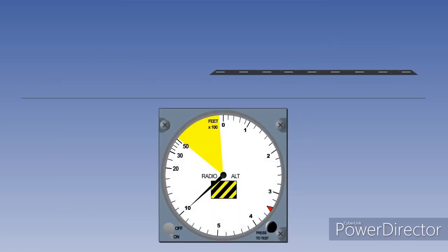Mode 6A operates between 50 and 1,000 feet and provides the crew with an oral warning if the aeroplane descends below the minimum decision height as set on the captain's radio altimeter. The oral alert "minimums" sounds only once and will be rearmed when the radio altitude becomes greater than that selected. "Minimums."